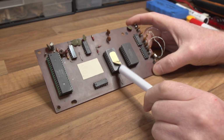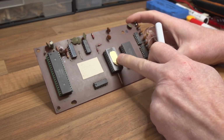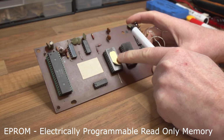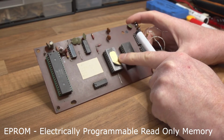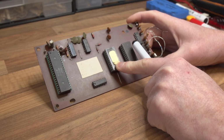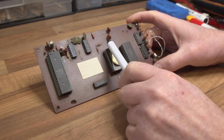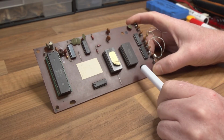Well, this is our ROM. This is an EPROM actually, and I've got a little sticky label on the top of it to stop ultraviolet going through. It's got a little quartz crystal window behind that sticker, and you can erase these chips using an ultraviolet light. So to stop sunlight from erasing the chip, put a sticker on the top, like a metallized sticker, and it stops the light getting in. That's what that's for. And I've written my call sign on there as well. So that's holding the program to do the entire job of running the computer.